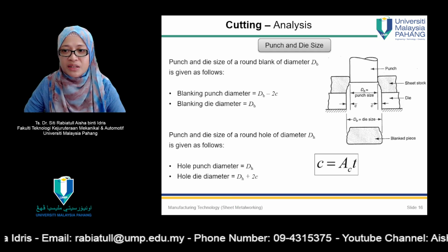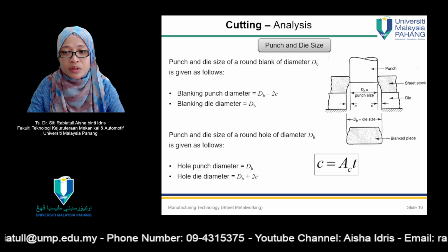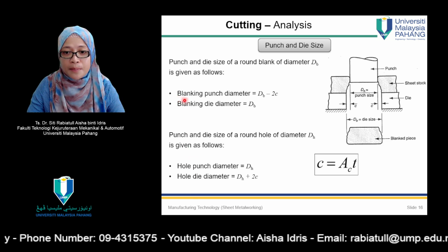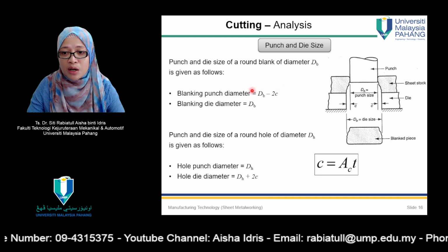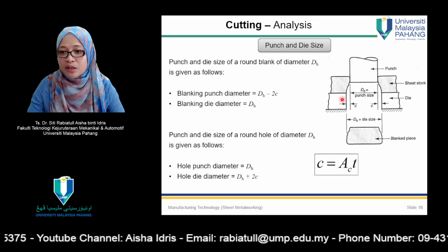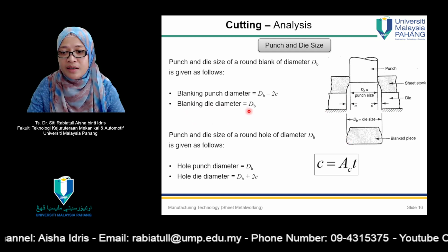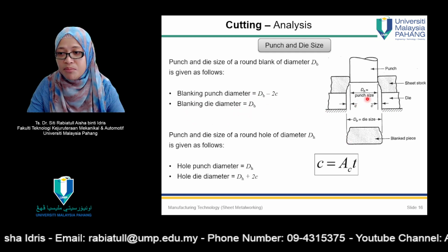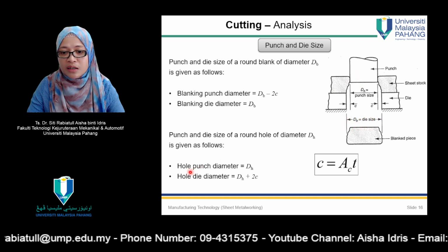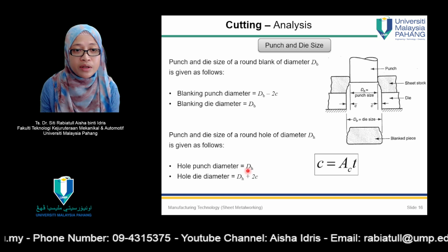Other than that, punch and die size. You need to know the terminology for punch and die. What is the blanking punch diameter, how to find it? Db, the die size, minus 2c. C over here is clearance, two sides of clearance. Blanking die diameter, Db. So this is Db, blanking die diameter. Other than that, hole punch diameter, Dh, hole diameter Dh plus 2c, two sides of clearance.